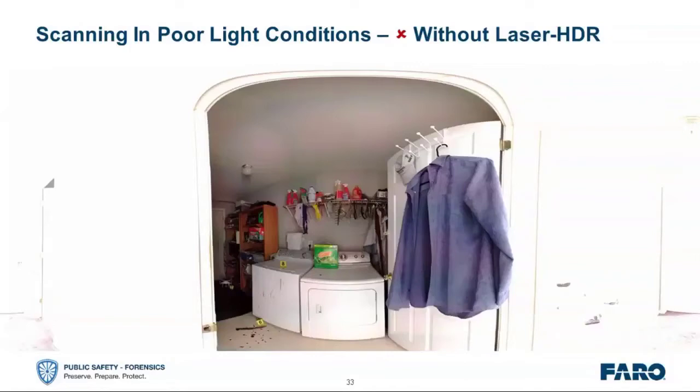If you're scanning in poor lighting conditions, understand that you can use laser HDR. HDR is high dynamic range. It's to set that greater dynamic range of luminosity or quality. It's basically bracketing. Bracketing is a method of taking several pictures at different camera settings automatically and in a methodical manner without the photographer stopping and making manual adjustments for each picture. Bracketing 2 or 3 stops down and 2 or 3 stops up adjusts your camera speed, which means you're moving 2 or 3 steps brighter and darker so you get the perfect light.